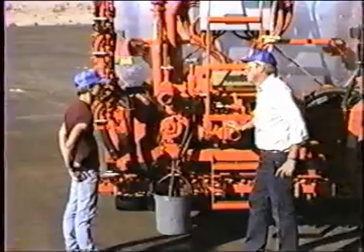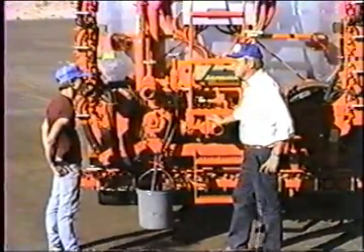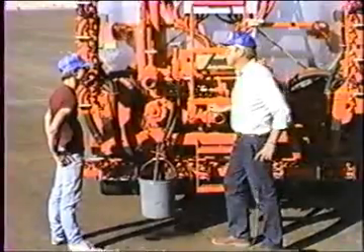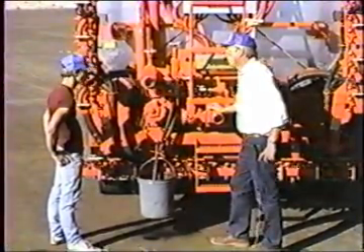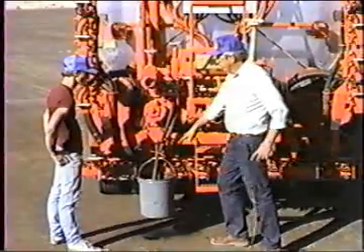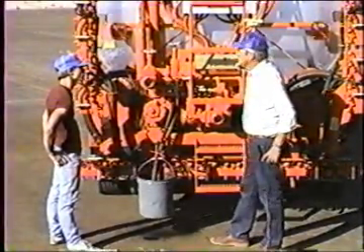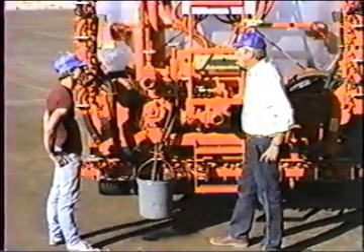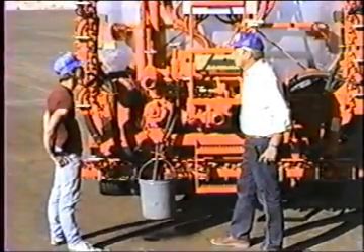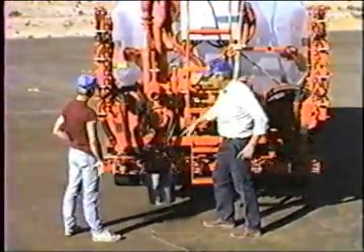Hot diesel cuts asphalt a lot better than cold diesel does. In fact, cold diesel will just bore a hole through the asphalt until it gets heated up, and then it'll start to mix the asphalt. After it's made a full loop through this spray bar, it's essentially gone through over 45 feet of 2-inch pipe with lots of crooks and crannies, and it's heated up by the time it comes back out.